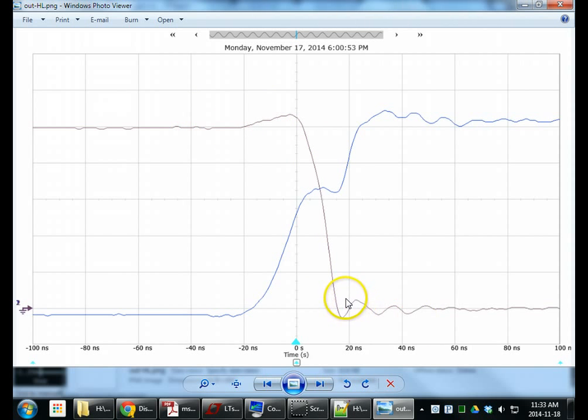And also we have to tie our ground leads as close as possible to the zero reference node on our circuit. So it's really, really tight. I used 3 pins on the breadboard, shoved them together, no extra wires, no jumpers or anything, just clipped right to the leads. It looks like a mess on the breadboard, but it looks beautiful on the oscilloscope screenshot.